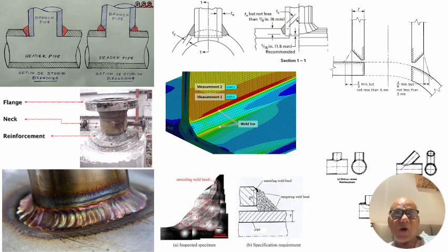So calculating where exactly we are going to find this unfused area, which is not possible to fuse unless we give a butt joint here, like in this nozzle, we do it. Normal fillets we just keep on top of it and weld only edge to edge and not penetrate into the thickness side. So these are all the considerations which are required to be brought in, and once we do that, I think our fillets will be good.